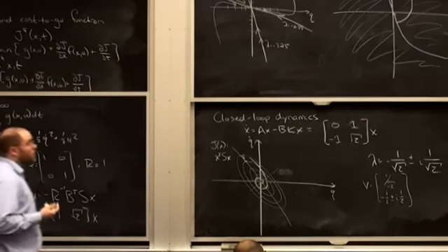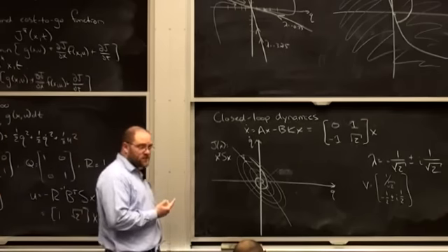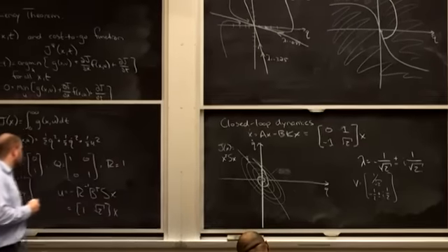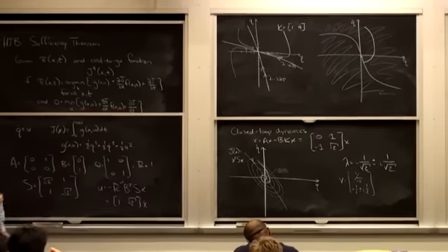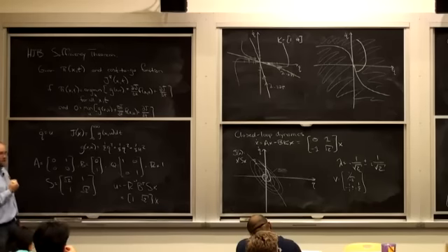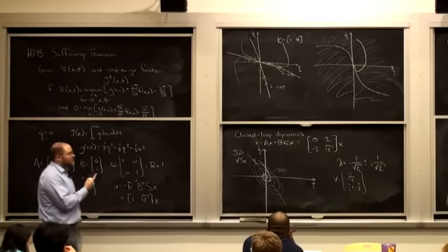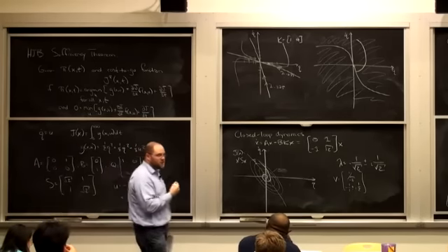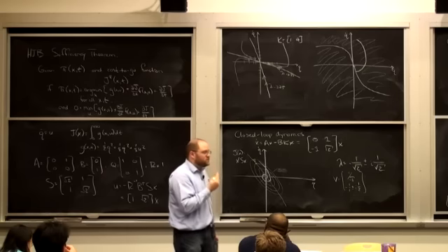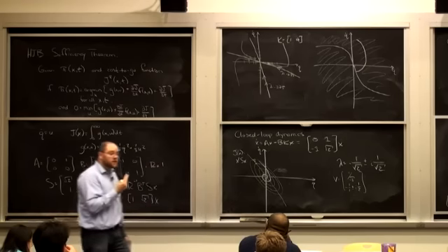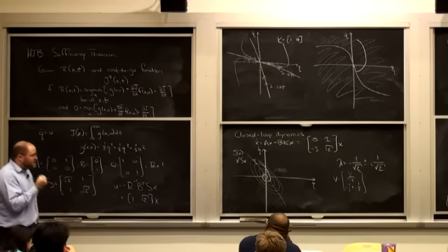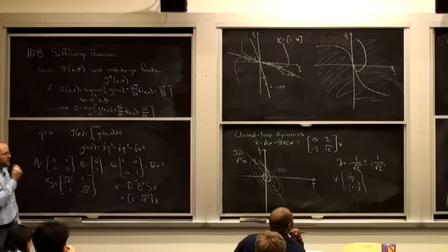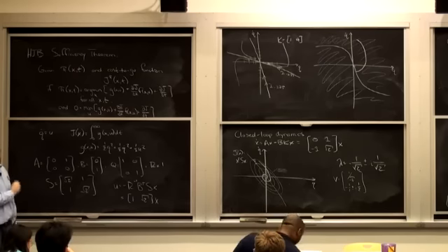When you have a linear dynamical system and a handful of cost functions, you can analyze them either by Pontryagin or dynamic programming, the Hamilton-Jacobi-Bellman sufficiency theorem. Those are really the two big tools that are out there. In cases, especially for linear systems, you can analytically come up with optimal control policies and value functions.